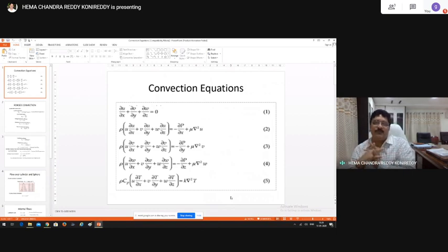That is the reason why people talk about aerofoil designs, aerofoil sections, aerofoil frontal area. That means when you are traveling at some speed, let the frontal area of the vehicle not offer too much resistance for air and therefore dispel the air, meaning the frictional forces will be minimum.